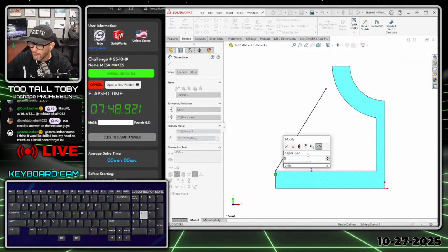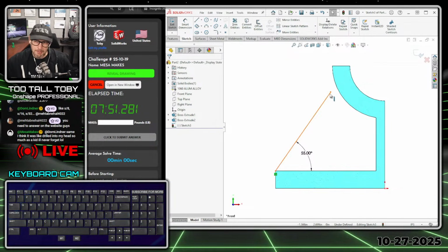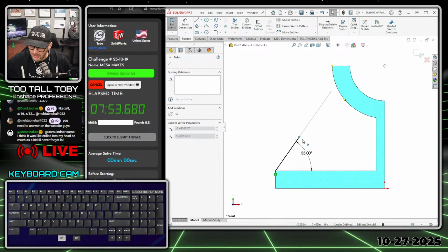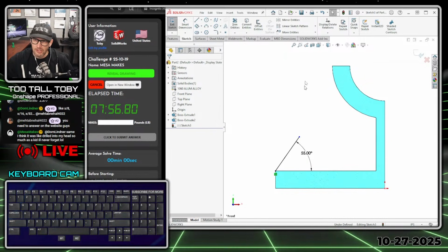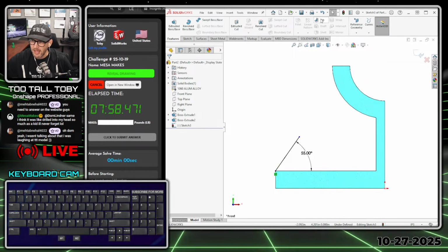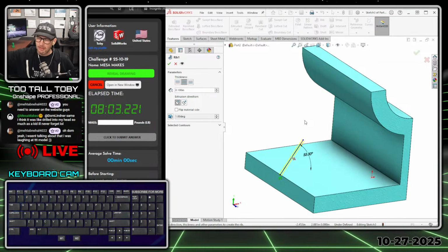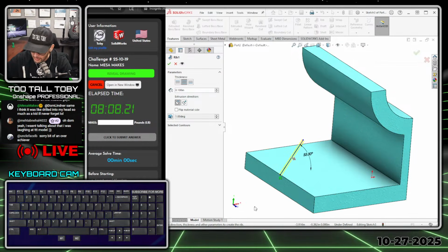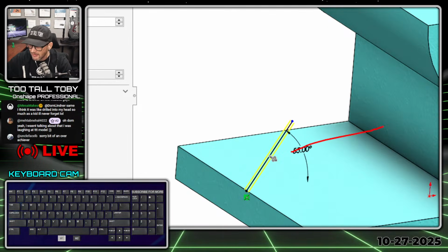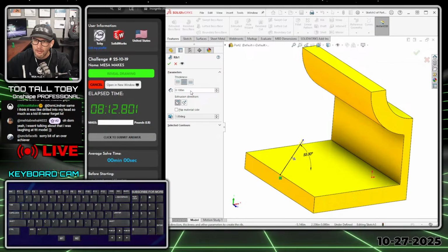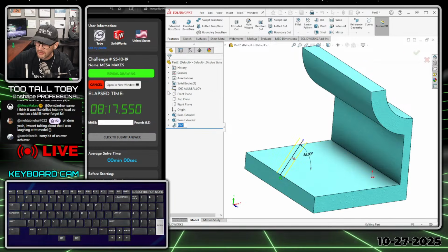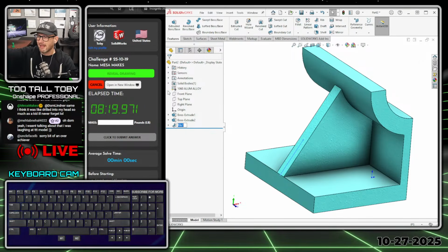Now, you'll notice here that I'm leaving this sketch short, and normally I probably would bring it up to this edge, but I just want you to see here, if I leave that sketch short and then I go to the command features rib, the power of the rib command is that the rib command extrudes up to next in 3 directions. So it'll take this line here and extrude it up to next in this direction to fill in all those gaps. So if I just type in the width of that, which is 3/8, enter, enter, you see the rib goes up to next, up to next, up to next, and we are good to go. We don't even have to connect that line.